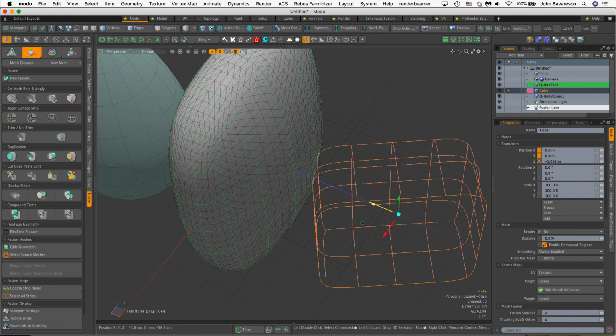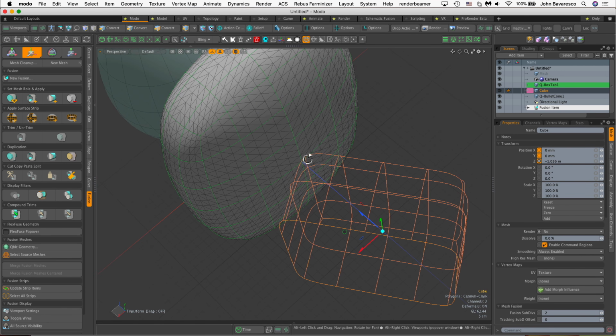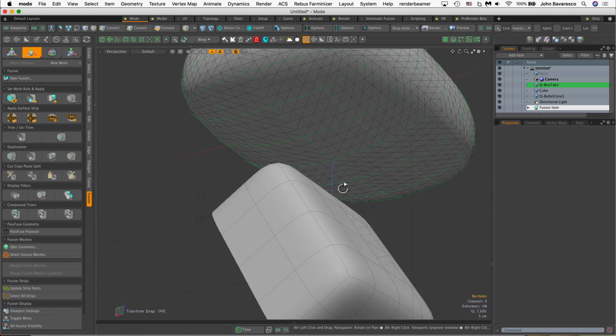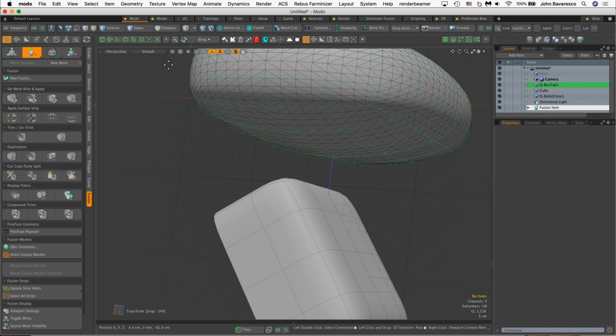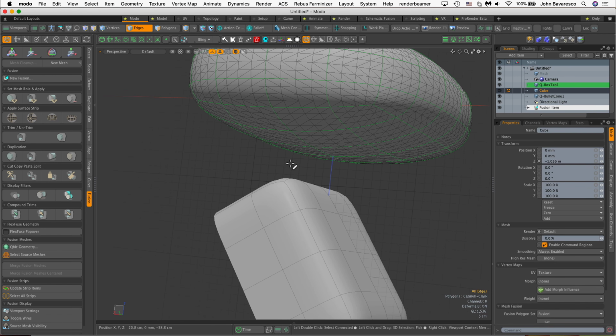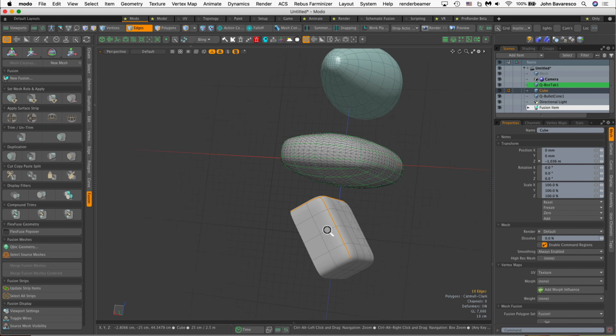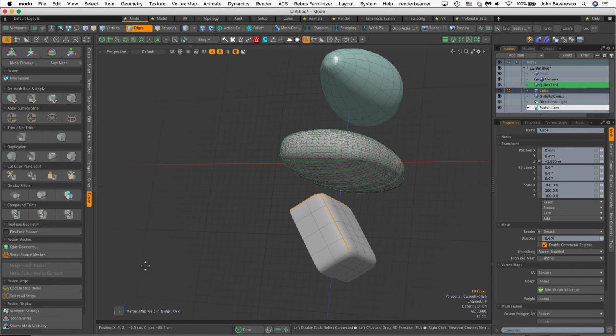But if I wanted this corner to be sharp, I could make that corner sharp. So let me undo that. I'm going to double click that edge, and that edge right there. And I'm going to hit Shift W to bring up my weights. I'm going to hit the K key to bring up the tools themselves. And since this is a Catmull Clark and a subdivision level of 2, if I hit 20 here, click in here, you'll see that that's a perfectly sharp corner.